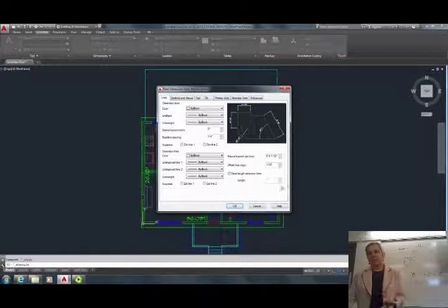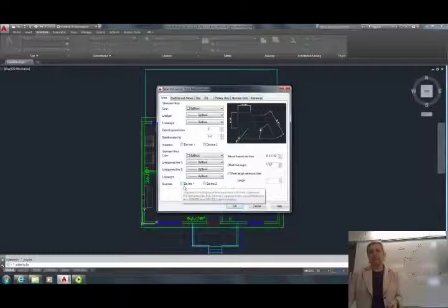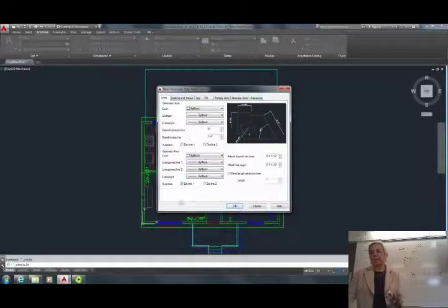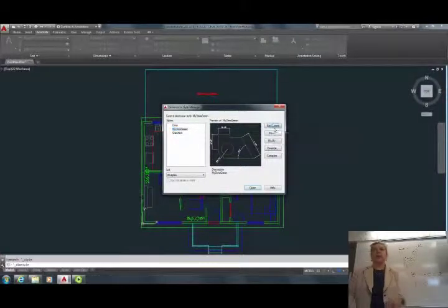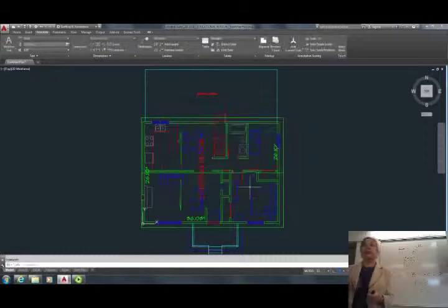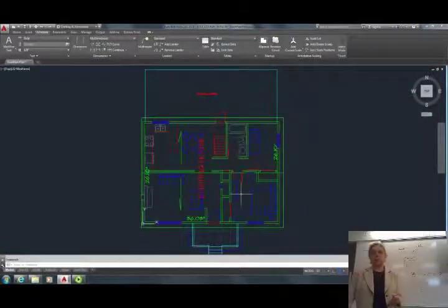Sometimes you can suppress, or you by accident have this on. Make sure that you don't suppress the extension lines. So I am on my last, and if I didn't forget anything, then I'm going to hit OK and click on my dimensions for green project and set it as current and close. So now that style is current, so if I do the dimension, that's what I should be getting. So let's see what we are going to get.